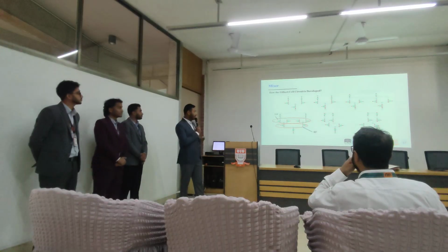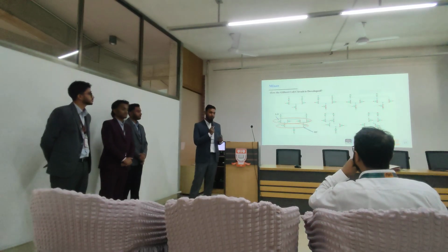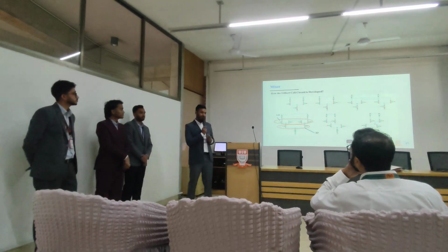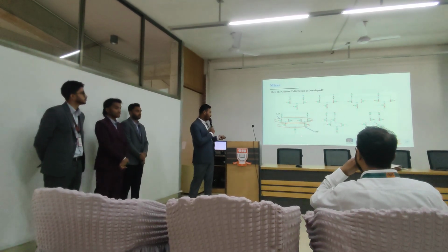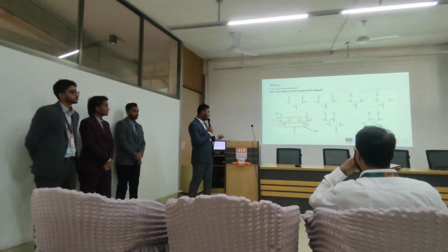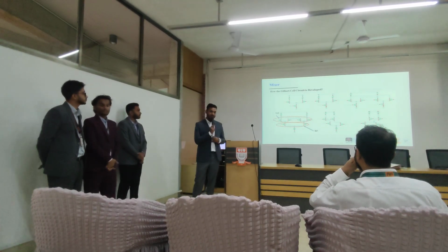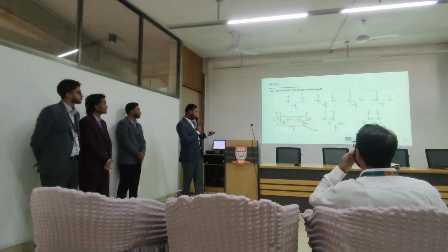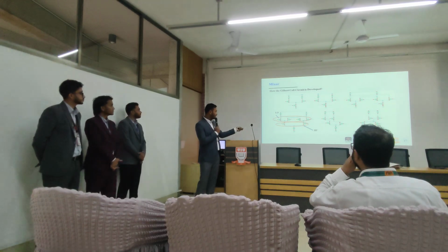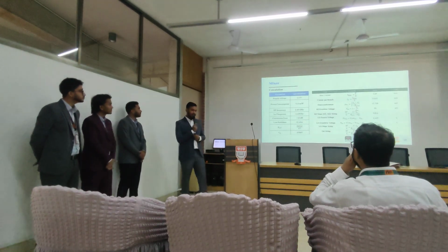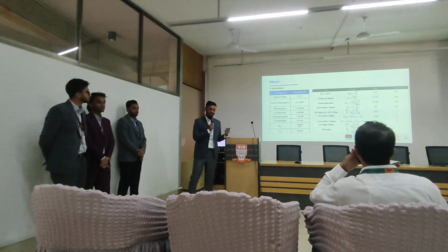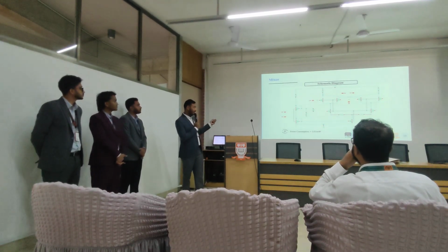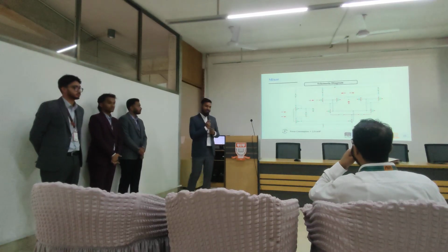To implement this, we use the most common and effective topology called the universal mixer. It consists of two typical parts: a differential amplifier, which takes the RF input signal, and a cross-coupled switching core, which is driven by the local oscillator. So next, here is the design calculation for the mixer based on the specifications, where we show the required component values, and this is the complete universal mixer schematic design.